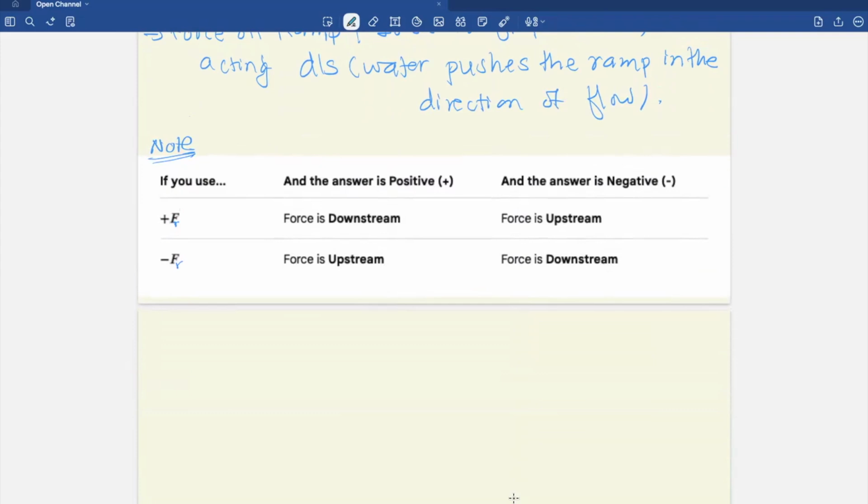And before I finish, I want to recap what we covered. In problem 1, we covered water surface profile. Remember the three questions: mild or steep, which zone, and what caused it. And for problem 2, we talked about circular pipes, and always compute Q full first, then use the hydraulic element chart.